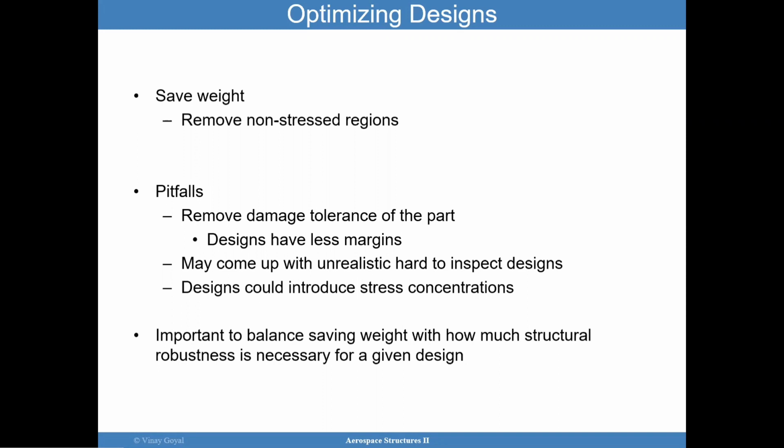The pitfall is that if you have a fairly good part that's robust, by optimizing the design, you may remove damage tolerance. So you may not have additional margins for defects. The designs will have less margins. So it may come up with unrealistic, hard to inspect designs. So you may come up with a part that's very hard to inspect.